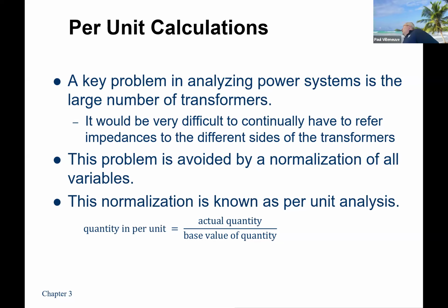And so, if we want to do some calculations for equivalency, it makes it much more difficult, because now we have a generator with a transformer and some sort of a load over here. To calculate what the current is out of the generator on the low side of the transformer, we're going to have to reflect this impedance using the turns ratio, right? So that makes the calculation a little more complicated, but not incredibly more complicated.